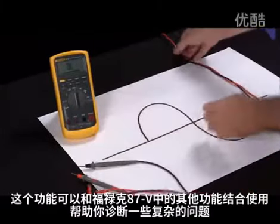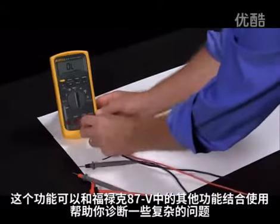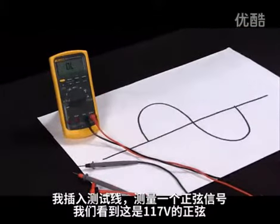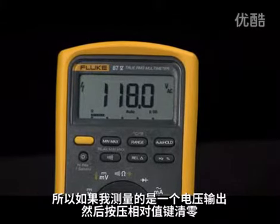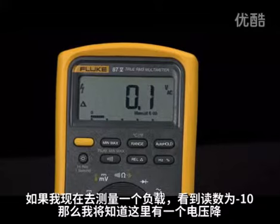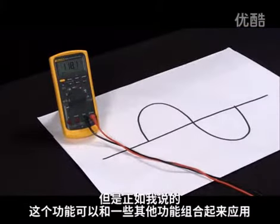This function, though, can be combined with several other functions within the Fluke 87 to help you troubleshoot some more complex problems. I'm just going to plug in and go to our sine wave. So here we have a 117 volt sine wave. If I was going to go to the source and then hit the relative, that goes to 0. If I now went out to the load and saw minus 10 volts, I would know I have a voltage drop. But as I said, this function can be combined with a couple other ones.